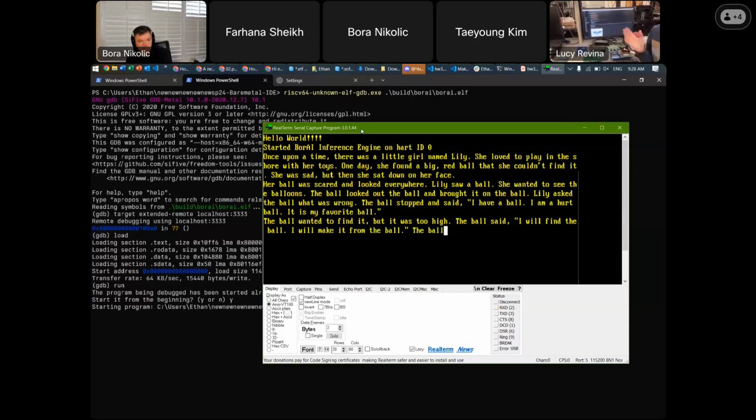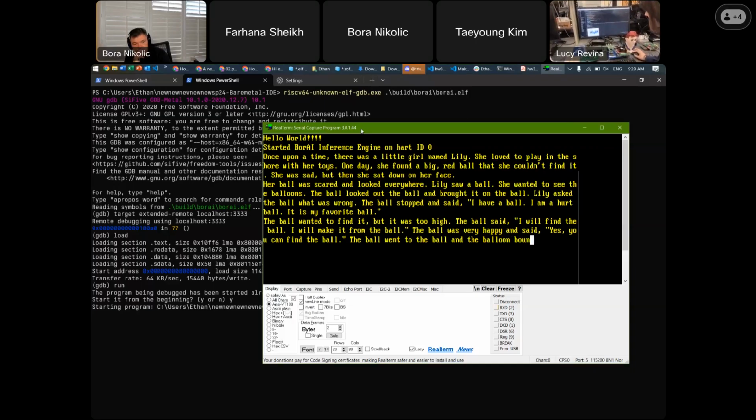But we don't want to show you an existing measurement, we want to show you live data collection. So here right now, you can see power without workload with the core spinning idle. We can consider that idle power at 50 megahertz, which is the default input clock rate. But we want to see how this differs when we're actually running the Llama workload, which is running right now, and how that workload looks in terms of power consumption. So again, with just a simple click, we see that we're getting a very different power characteristic, which is pretty interesting.